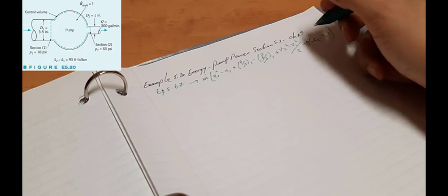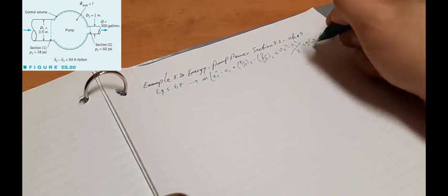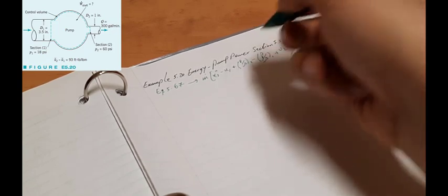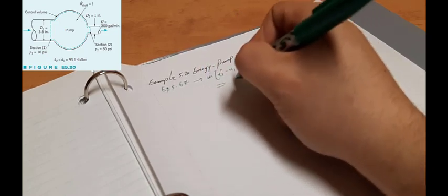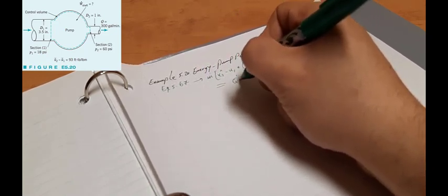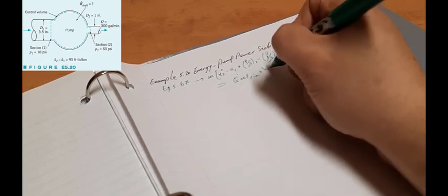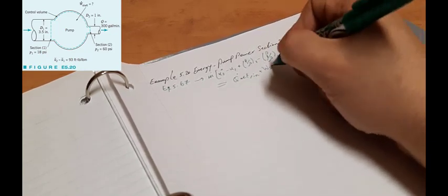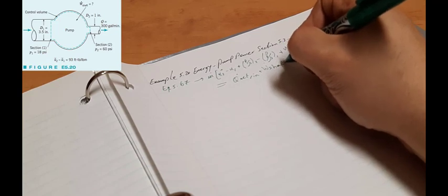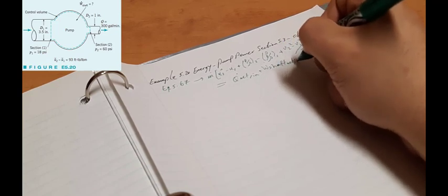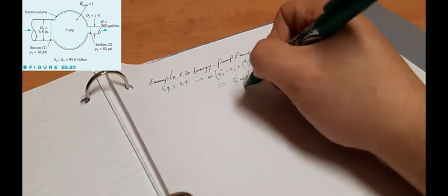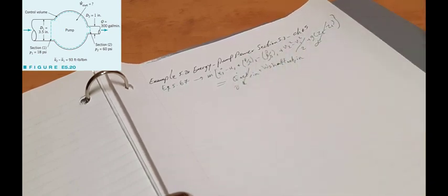As long as we don't have any elevation, this term is going to be 0, and the total equation is equal to Q net in plus W of the shaft, work of the shaft net in. Since we are having adiabatic performance, it's going to be 0 in here.